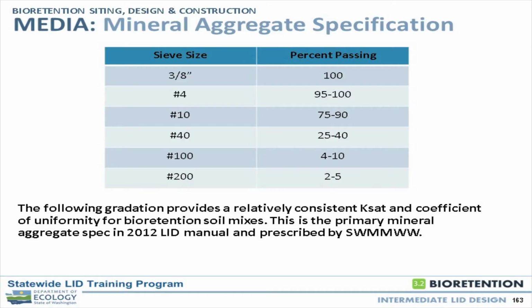So these are some of the guidelines that come along with the default mix, and we're going to talk more about that. Here's the particle size distribution for the default sand. It's in the manuals. And we found that this particle size distribution, a coefficient of uniformity of at least 4, and mineral fines at about 2 to 4%, less than 5, gets you in a pretty solid ballpark as far as the permeability. It varies, but it's reasonably close. That's just a little bit on the default mix.